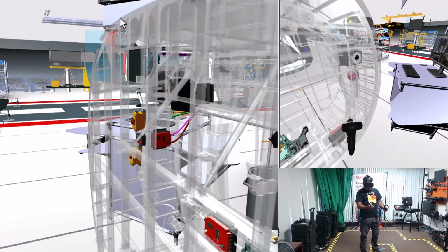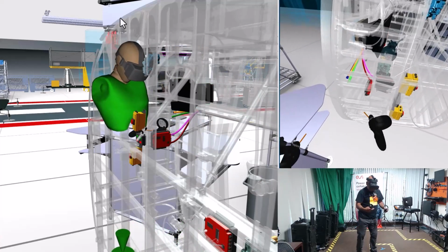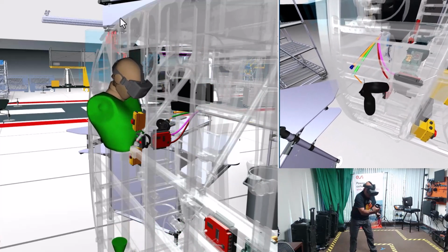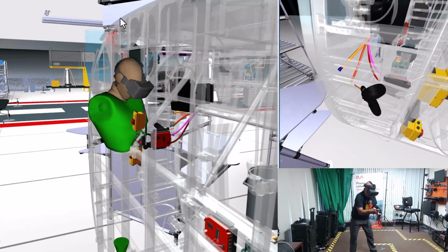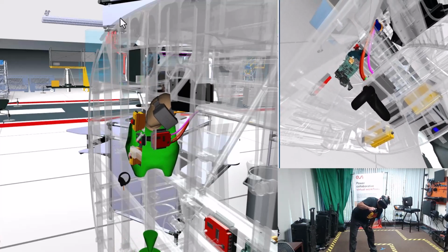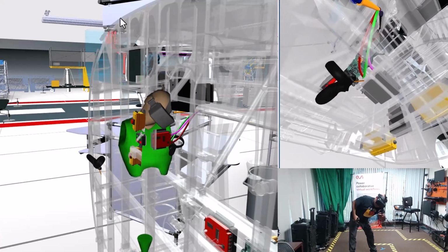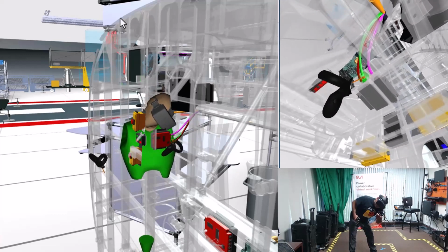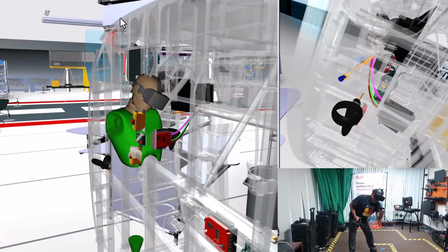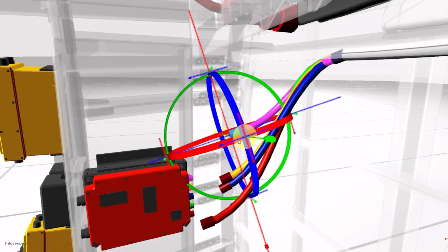This is less common than you think because it turns out that many times when CAD engineers are drawing those bodies, they're instead drawing perfect cylinders or perfect pipes that don't properly represent the behavior of cables and hoses and wires in the assembly. Therefore, it's very necessary for us to validate the behavior of those cables. Do they have enough length to be plugged in? Sufficiently short length to prevent being pinched or trapped.